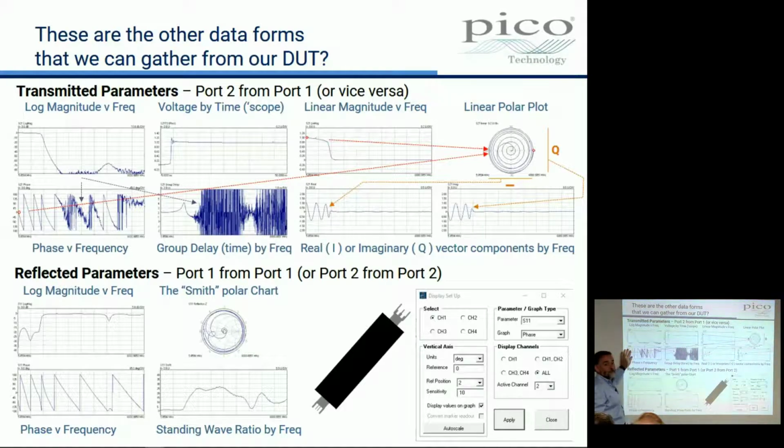What would I have to do to improve the noise? Any ideas yet? Mentioned it a couple of times. Okay, I could change the bandwidth of my acquisition. I could drive bandwidth down to say 50 hertz, 10 hertz, and that noise floor will go down. You'll see. So, phase. Now, let's map that to a polar plot.